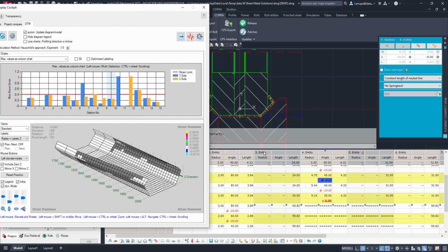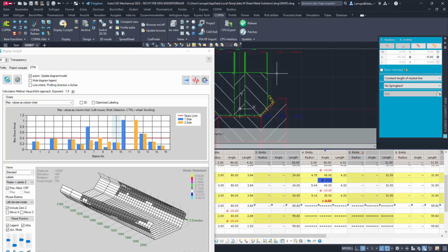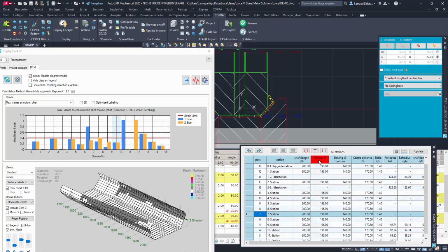how the changes we do in the spreadsheet table affect the unfolding, even the roll diameters. So if, for example, I go to the axis configurator, and I change, of course the working station is the bottom one, so if I change to 60, I have to update. No, that's it. So we saw here live how it increased the longitudinal elongation because of the change of the bottom diameter. So I think this is a great new feature we have to show to all of our prospects.